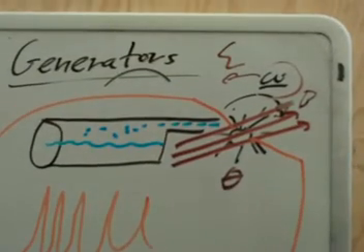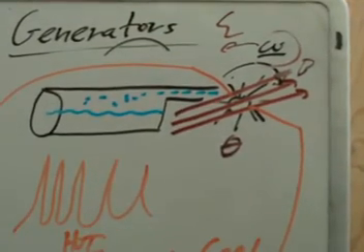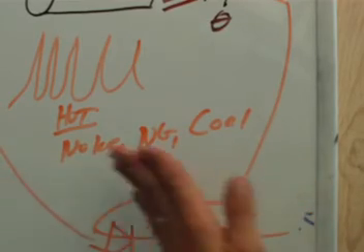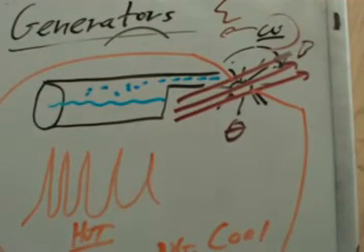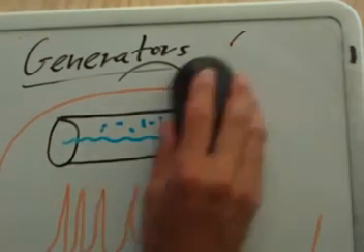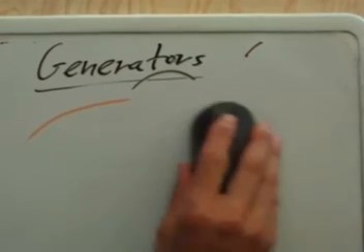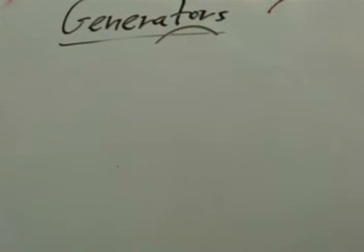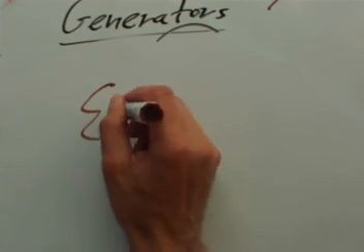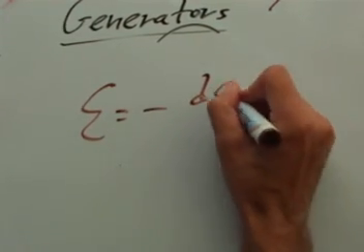And of course it's sinusoidal, as we saw here, so one minute the current in these wires is going to be to the left, the other minute it's going to be to the right, but that's the name of the game for generators. Get that loop to spin by virtue of escaping high pressure steam, and as long as it spins, you have an omega, which makes the theta, the angle between the loop and the magnetic field, change, and your EMF comes out.